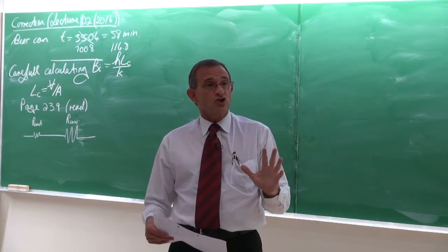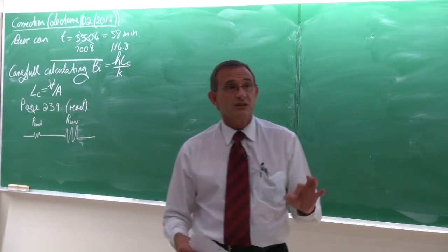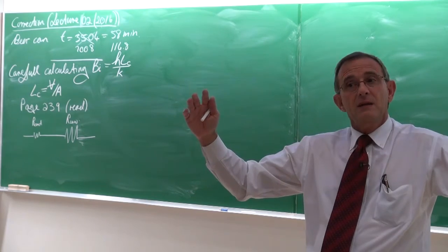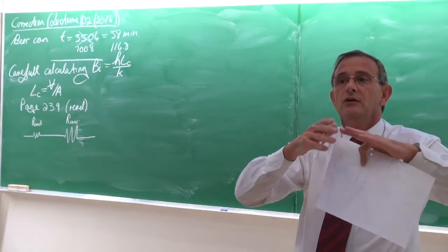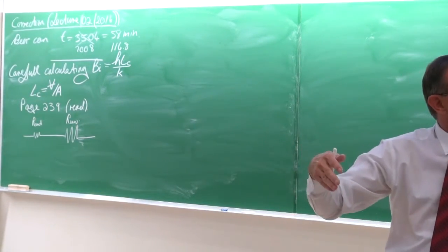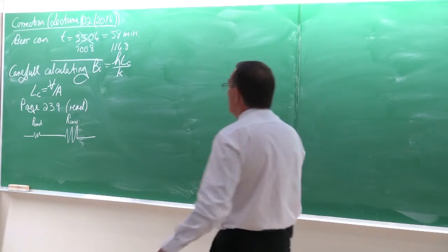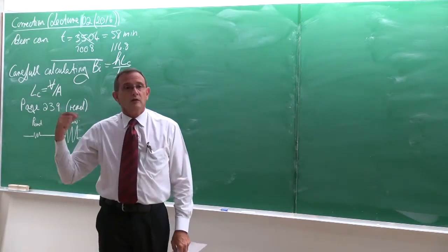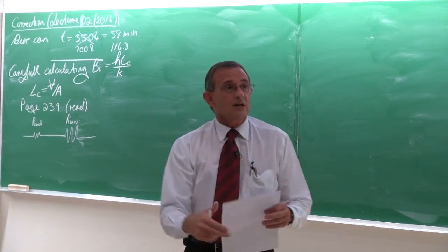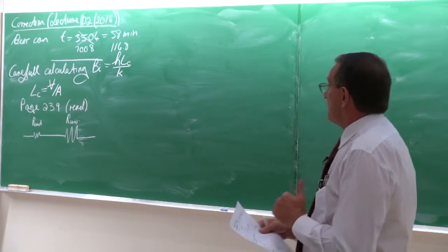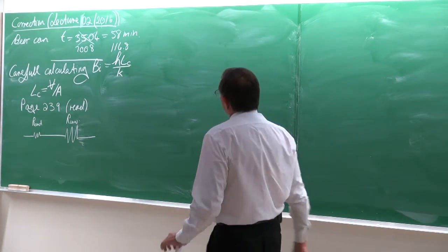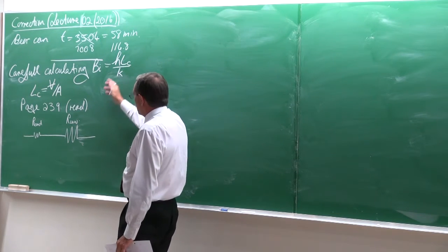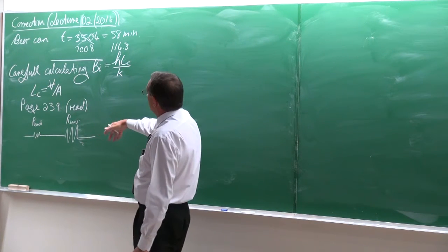The lump system approach, unfortunately, has a very important limitation, and that is whatever the body is, the temperatures everywhere in the body would be the same. That would be the prediction. And that is the reason why this term must be very small for that assumption to be valid. So in general, we've said if we look at the Biot number, to get applications where the Biot number would work well is of course where the Biot number is smaller than 0.1.